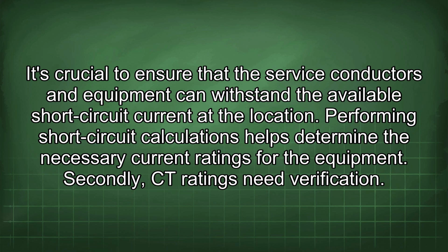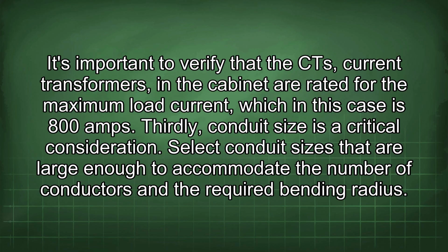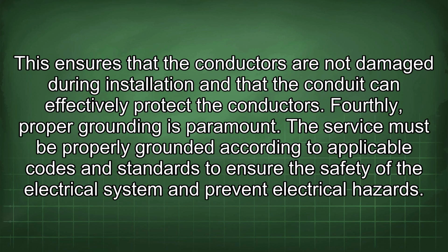Secondly, CT ratings need verification. It's important to verify that the CT current transformers in the cabinet are rated for the maximum load current, which in this case is 800 amps. Thirdly, conduit size is a critical consideration. Select conduit sizes that are large enough to accommodate the number of conductors and the required bending radius. This ensures that the conductors are not damaged during installation and that the conduit can effectively protect the conductors.